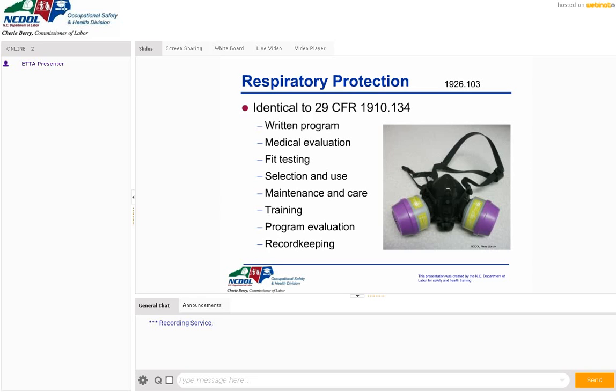The other thing is fit testing. If you don't have a proper seal, then you are not going to have a good respirator that's going to seal you from the elements. It's going to give you a false sense of protection, which is not good. You need to have a good seal, and how we determine this is by actually doing fit testing, either quantitative or qualitative fit testing, but one or the other. We want to make sure you make a good seal.